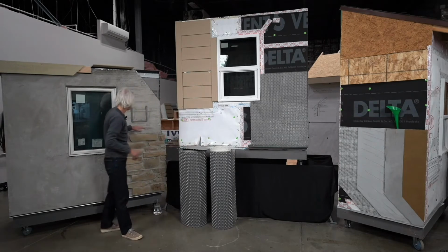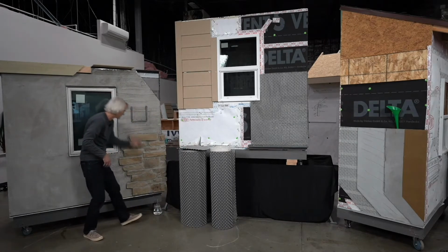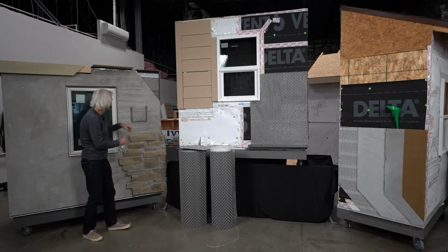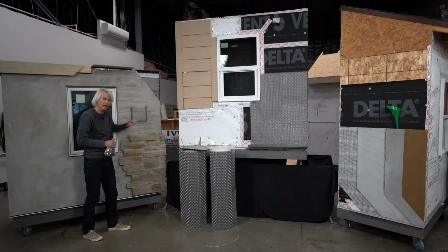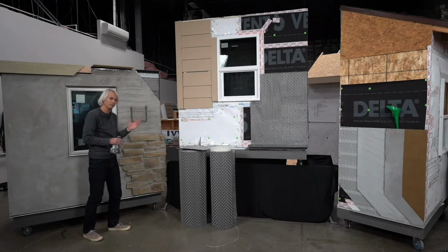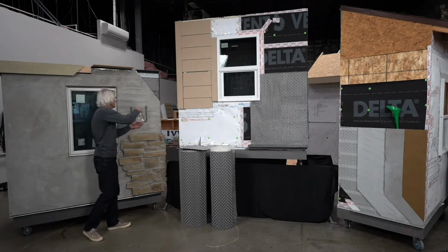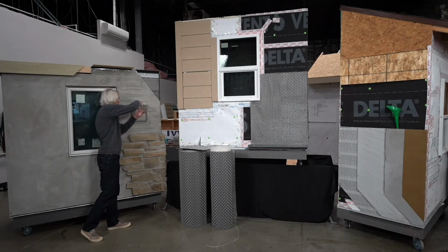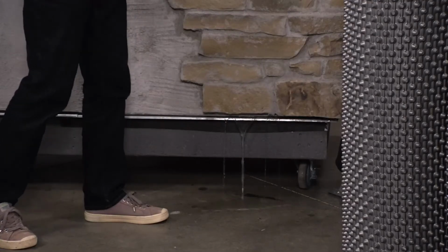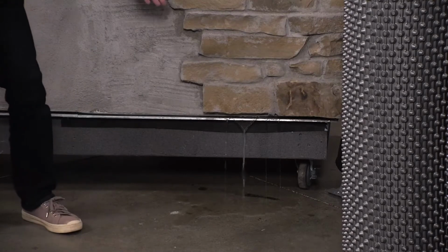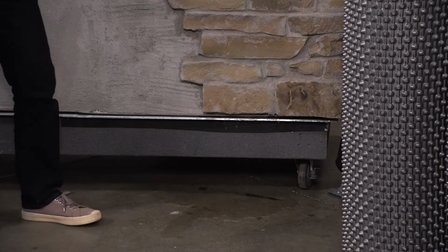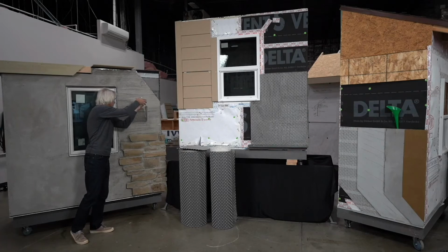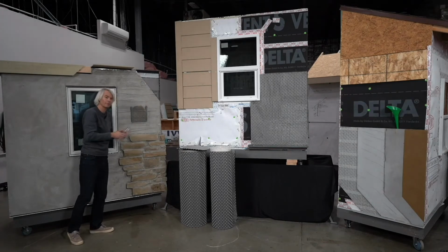So, all things CI Live, we built a little acrylic box here, and we've drilled several holes into just the scratch coat to see how fast we could get some water drainage on the front side of this rain screen product. So here we go. I'm going to dump this water in, and you'll see it'll uptake into those holes. This may take a little bit longer for it to come out than the other one, but it's not taking too long. As you can see, there's the water spinning right out of the bottom of that wall. So we've got accelerated or rapid drainage on the front side as well.